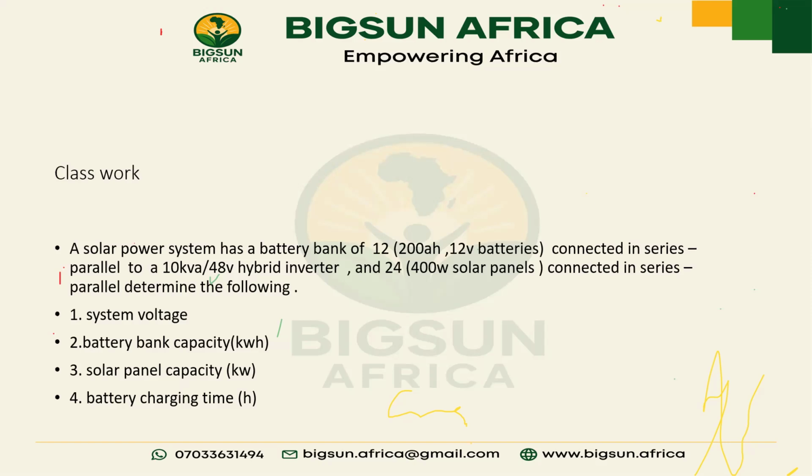Okay, can we quickly do this last one here? A battery bank of 200 amps, 12 volts, connected in series parallel to a 48 volt hybrid inverter and 24 pieces of 400 watts. So let's assume we have already established that one single 12 volt 200 amps is 2,400 watt hour. What we are going to do in this case is just 2,400 watt hour times 12, which is going to give us what?